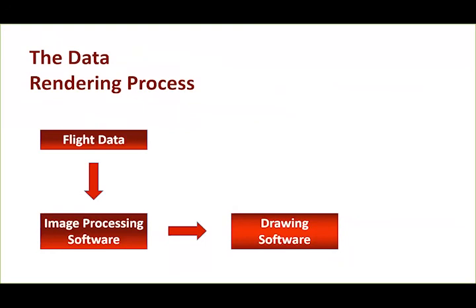Aside from doing a good presentation or a good rendering to show clients or the court, if you want to get down to the nitty-gritty portion of scaling, drawing, and additional overlays, such as bringing in your total station data or your at-scene data with your photos taken by GPS, like the multi-sensor processing, then you're going to transfer that final product, like an LAS from your third-party software, and import that into your drawing software.